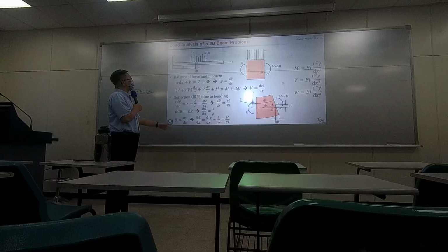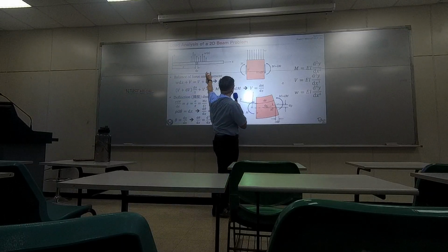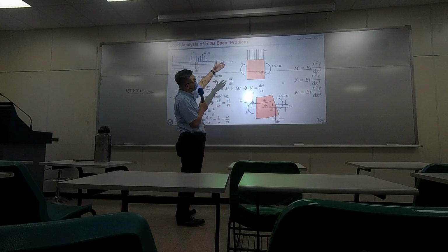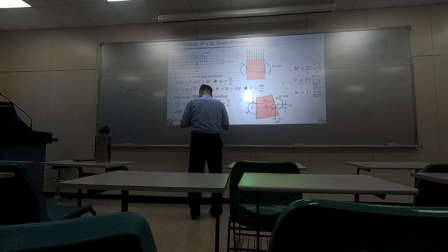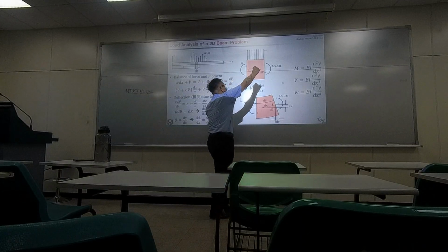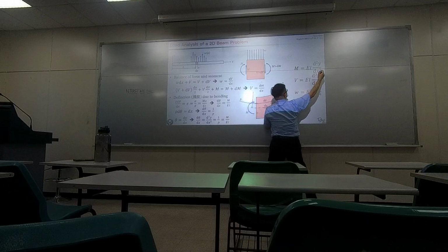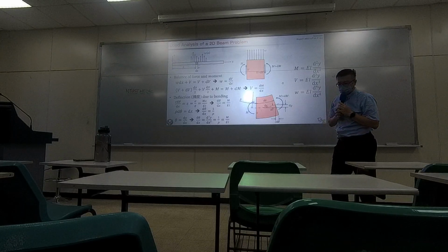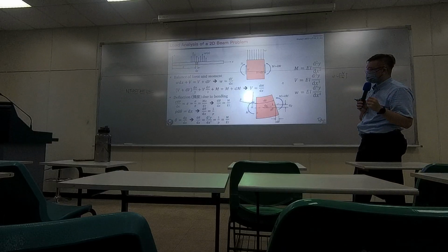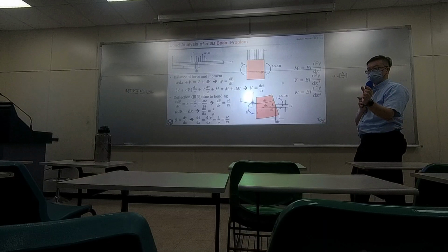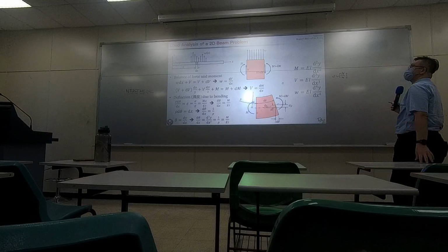Okay. So now we are focusing on this tiny slice, tiny cut of the beam, and we have distributed loads on top. The unit of the distributed load W is Newton over meter. So it's not Newton only. It's how much load is being applied within a certain linear area.